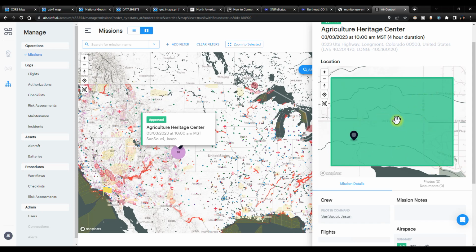This is where we're going to include the Propeller Aeropoint over on this side of the map. We're going to have an existing NGS survey benchmark on this side of the map. Those are going to be our 2 checkpoints for our survey once we get onto the field. So let's go ahead and head out to the field now, and we are going to fly this mission.